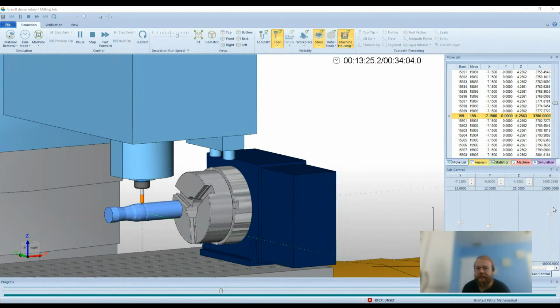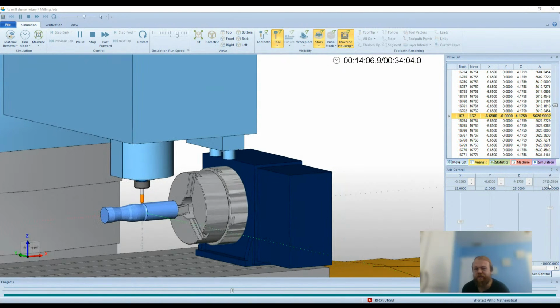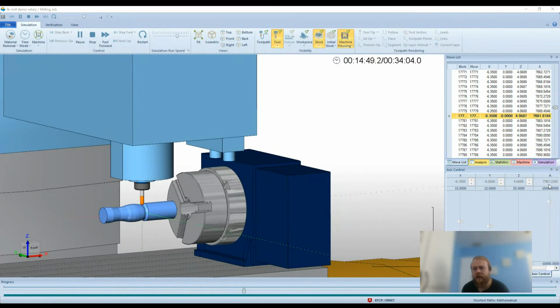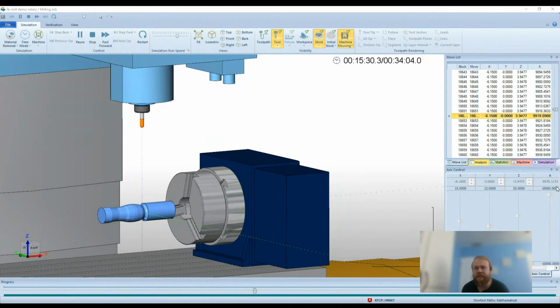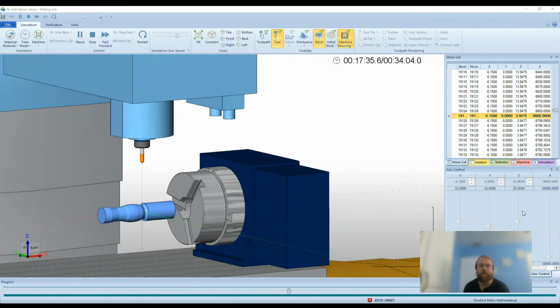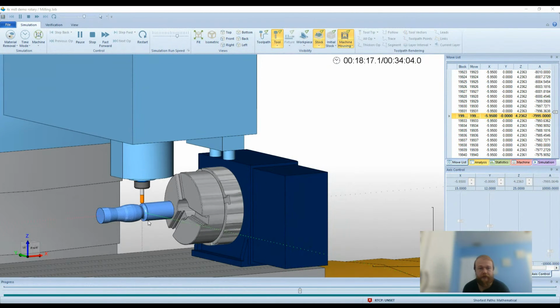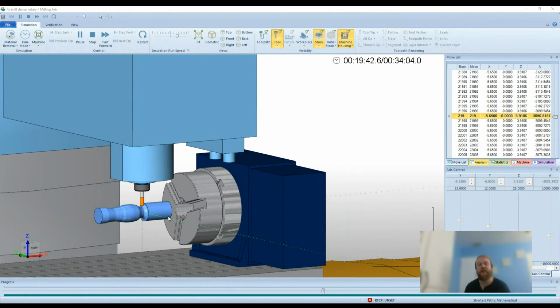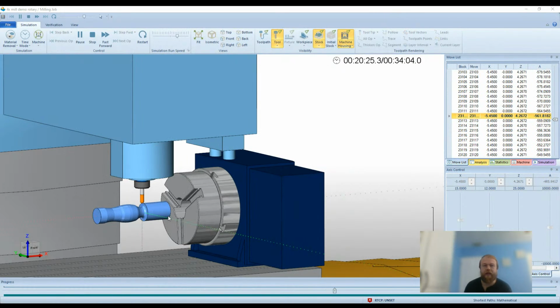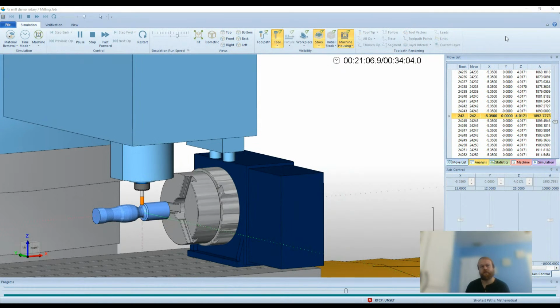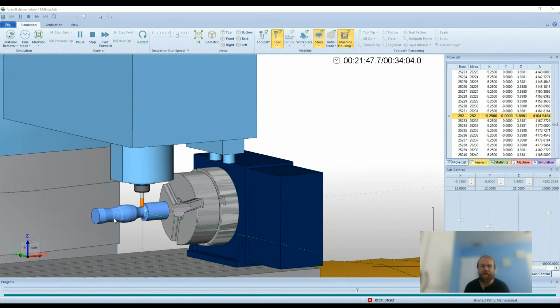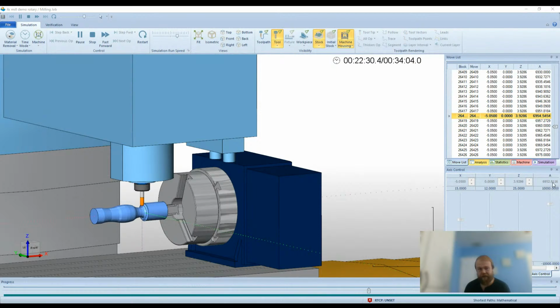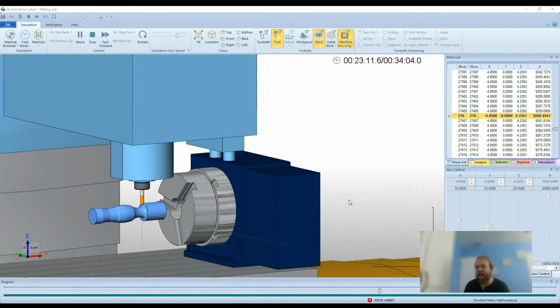The best answer I could give is because we always need to know that A-axis location, so that if there's going to be any indexing on the part, for example, we need to go to 90 degrees on one side of the part, we can reference it for another milling operation. A lot of machines have limits to the A-axis for that reason, and that's why we have it at plus or minus 10,000.